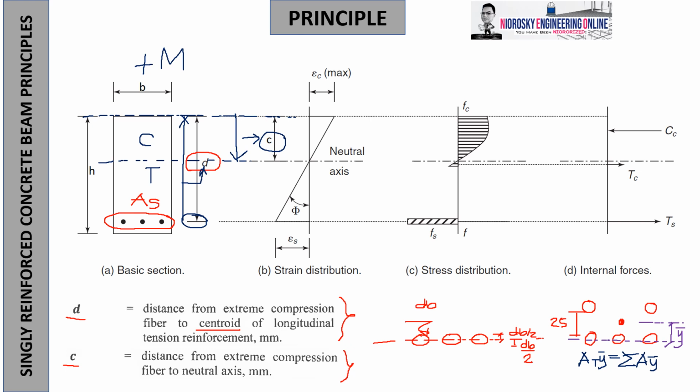Now, notice that if you recall, we have two stages of cracking, no? There's linear cracked and linear uncracked. But what is really happening on the beam when we subject it to an actual stress distribution is found out already by so many times due to testing, laboratory tests. So this is the stress block that we need to understand. It is somewhat like a combination of parabolic, linear, and somewhat elliptical on some portions.